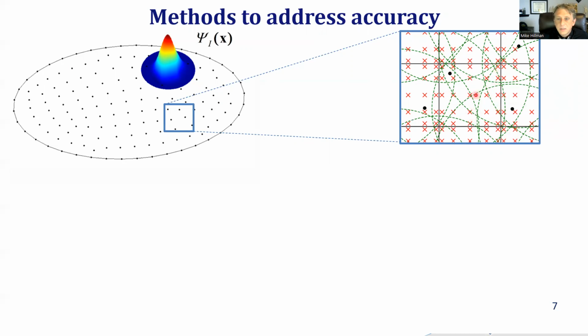Okay, so basically in the weak form, I'm going to have the test function and the trial function, the product of those two, right? And you're trying to integrate all these little pieces, right? That's the interaction between the points, these overlaps, right? So you're trying to capture all these, and you can see why I need very high order Gauss integration to get good accuracy. I would try to get all these little overlaps and pieces, and one way to address that would be to align these cells. You can see that just the fact that these cells are not conforming to the support is going to cause a lot of problems.